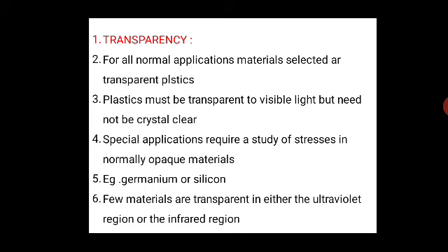Polariscopes can be constructed to operate in either of these regions if advantages can be gained by employing light with very short or very long wavelength. However, for stress analysis purposes, visible light polariscopes are quite adequate. And so this is the most required property for two-dimensional photoelastic analysis.